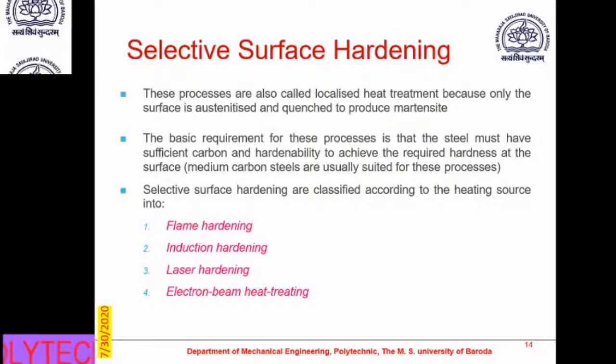Laser hardening gives you an accuracy of about 1 mm. So if you want a small surface of around 1 or 2 mm throughout the circular part, or you want to make a strip of around 5 mm by 15 mm that requires a different hardness compared to the rest of the part, laser hardening can be used.